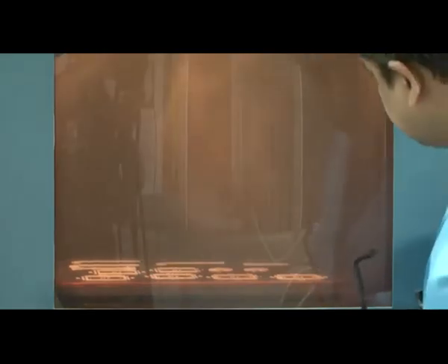So we now want to do this auto home, so we just need to enter for doing this command, and you can now see inside, if you have a look at it, the stage is going up, and there is a positioning of the nozzle with respect to the stage happening within this machine, so that you can have a home position for the workpiece with respect to the nozzle within the machine system. So it is still homing the XY gantry and the Z stage. This process will take a little more time.